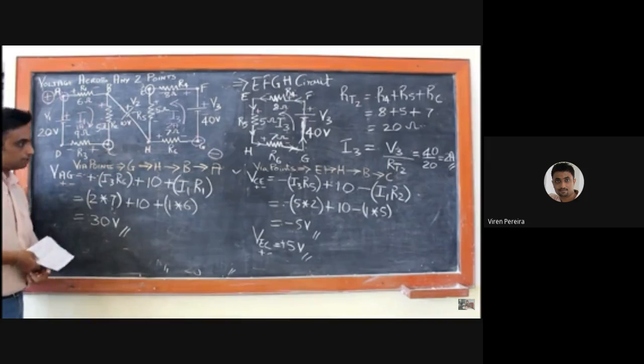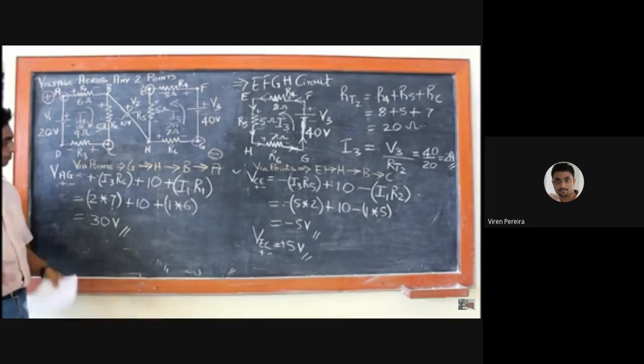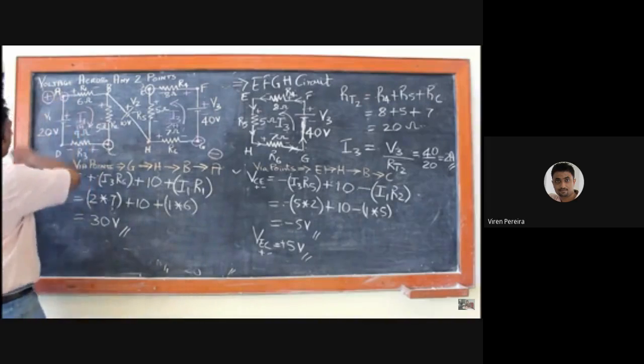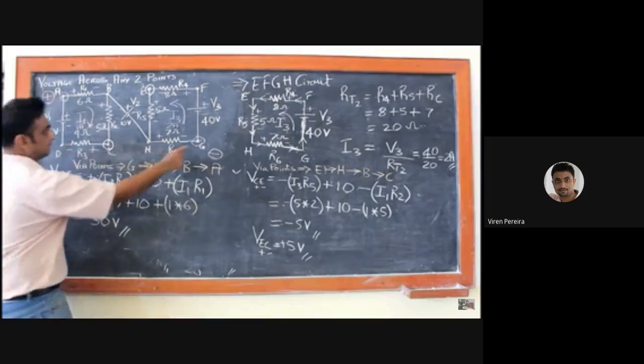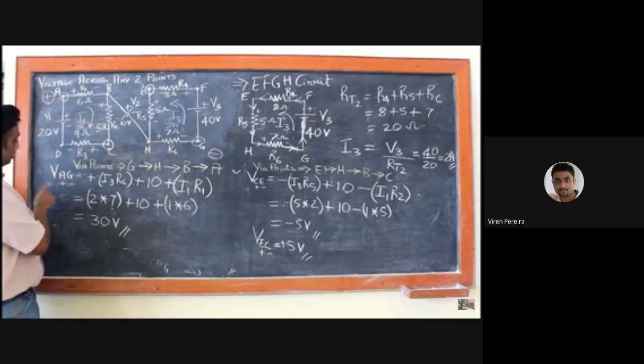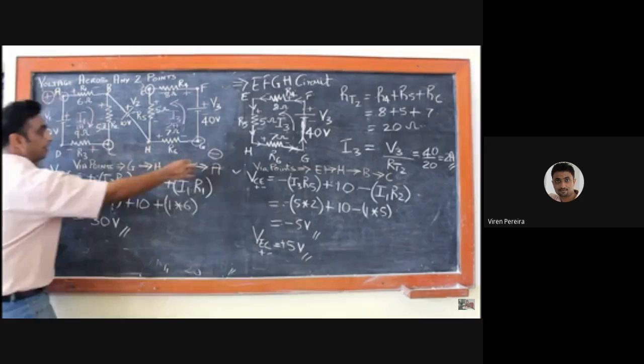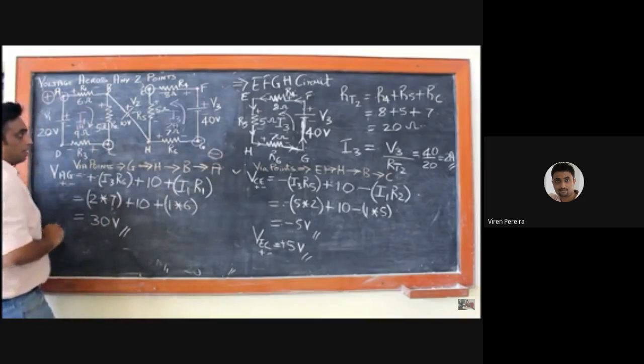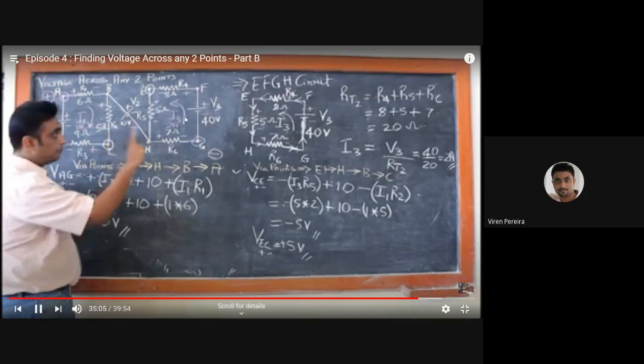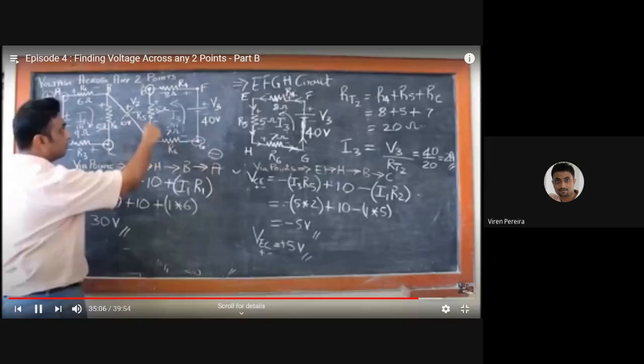So coming back to this system, what I have followed is, always note your points. First A and G, say it is for VAG. Always A, the positive terminal of the multimeter will be the first terminal, so that's why I took this as positive. And the second terminal of the multimeter will be your negative terminal, which will be connected across G. So I took this as negative. Highlight positive and negative. Now, to get the polarities, simple technique, we have already found out all the polarities.